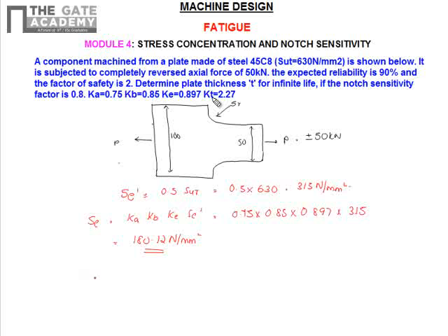And for this kind of loading, the maximum stress is given as Kf into sigma O, where Kf is equal to 1 plus q into Kt minus 1.